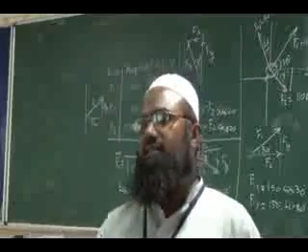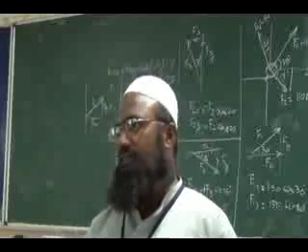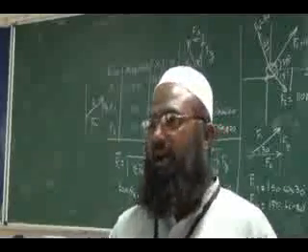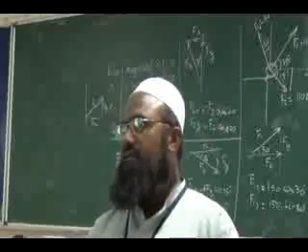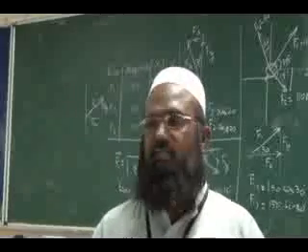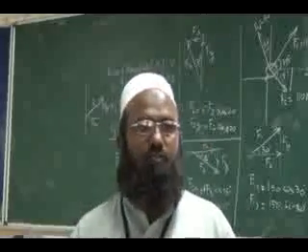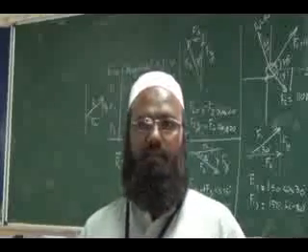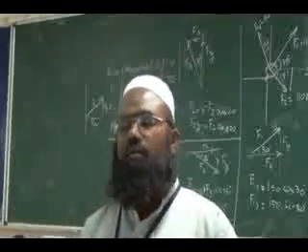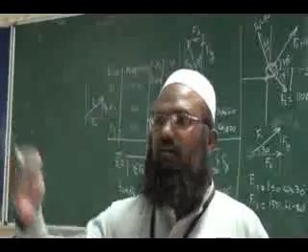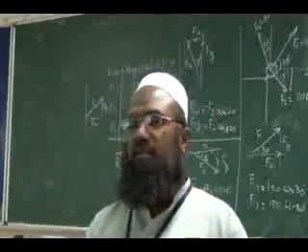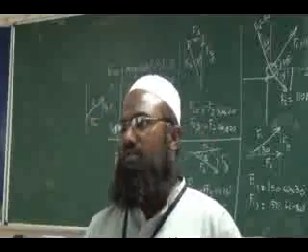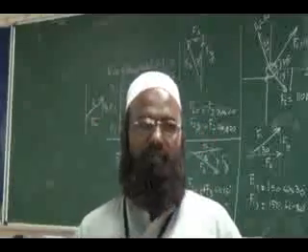So in today's class, we have seen how to resolve the forces into two components and how to add them numerically. Numerical approach of adding two vectors, two forces or more than two forces by using cosine law and sine law also we have seen. And the unit vector approach. So tomorrow, next class, we will see the Cartesian vector in space, the forces in space and equilibrium of the particle.